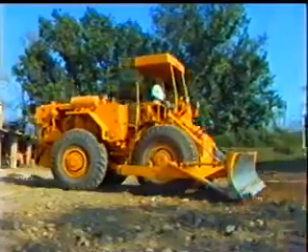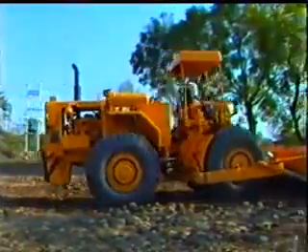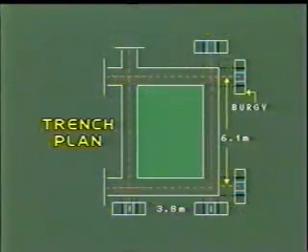Layout and construction of burjis. For starting any construction, the site is cleared either manually or using mechanical earth movers. After clearing the site, exact position of the foundation trenches is marked on the ground. The graphic shows the foundation trench layout plan along with the location of burjis.